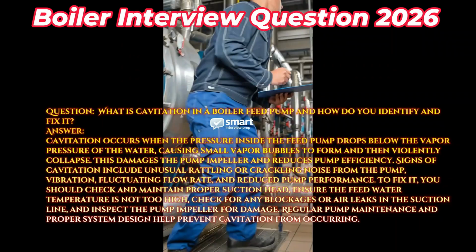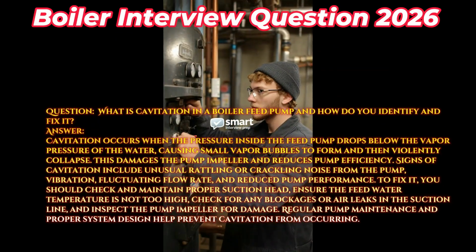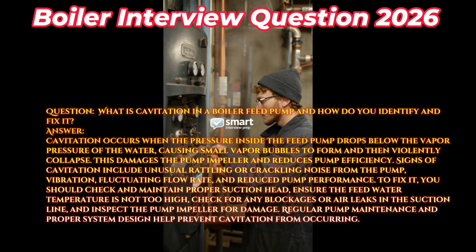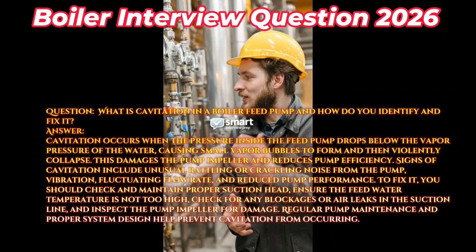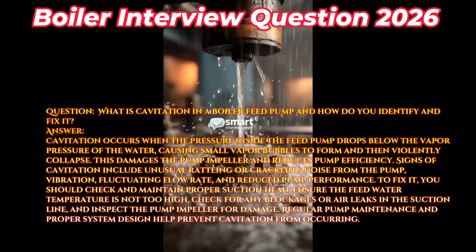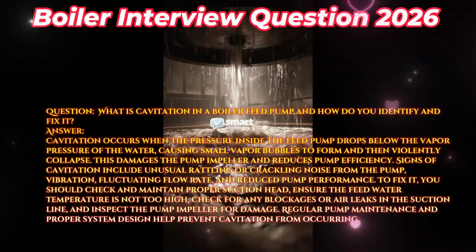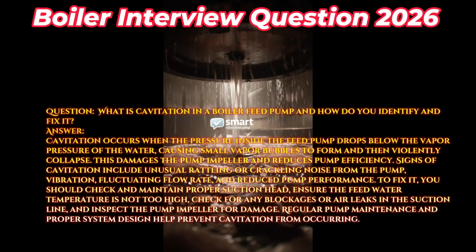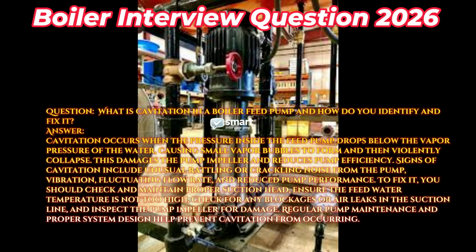Signs of cavitation include unusual rattling or crackling noise from the pump, vibration, fluctuating flow rate, and reduced pump performance. To fix it, you should check and maintain proper suction head. Ensure the feed water temperature is not too high, check for any blockages or air leaks in the suction line, and inspect the pump impeller for damage. Regular pump maintenance and proper system design help prevent cavitation from occurring.